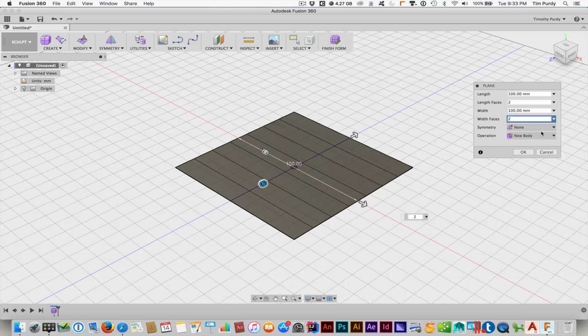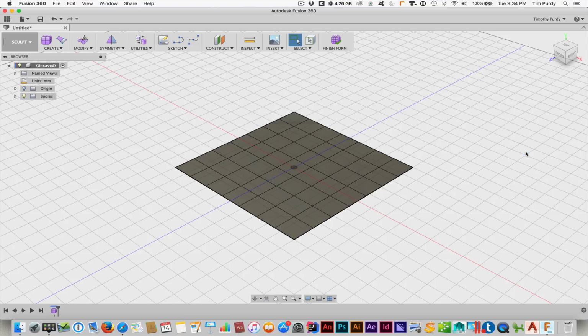And so 7 to me worked pretty well, and I do it consistently or the same on both the length parameter and the width parameter for the number of faces with this. Okay, so that'll give us kind of those faces there to pull, and then we'll sculpt down. Won't worry about symmetry right now, although you could use it in doing something like this. Okay, so let's hit OK to that.